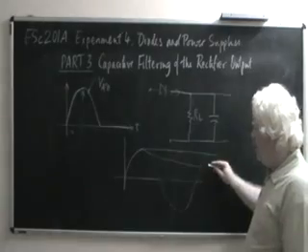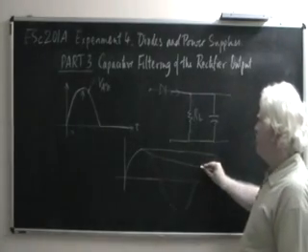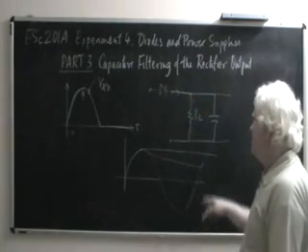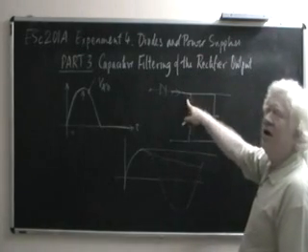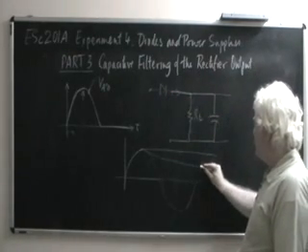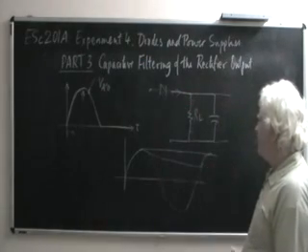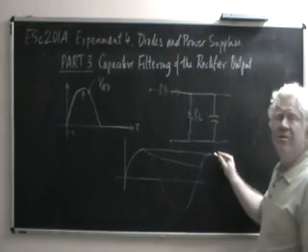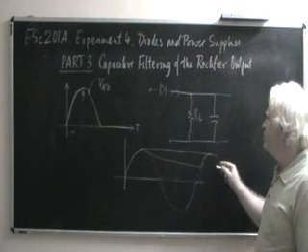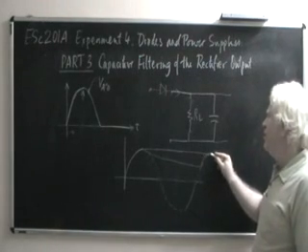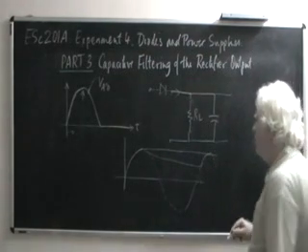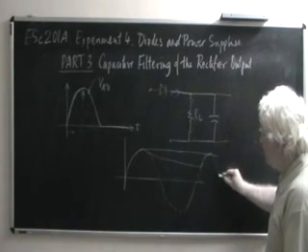this capacitor now starts charging once again, because the diode is again forward biased, because its cathode end is at a lower voltage than the anode end, so it starts charging once again. It charges up to this point, but again turns the diode off, because now the capacitor is charged up to here, and the rectifier input voltage starts falling. So this repeats.